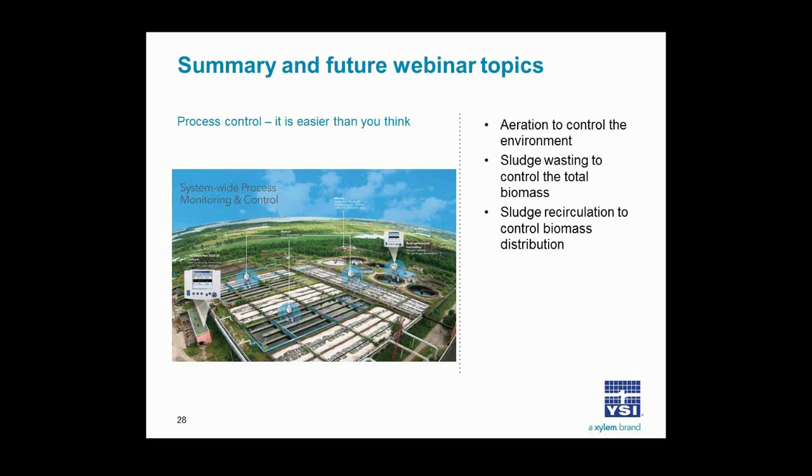Yeah, thanks for the question. Well, it's going to depend on what you have to do. If you have to do nitrification, for example, going back to the chart we showed earlier, the target SRT would be more than 12 days, and I think that's pretty much in line with a lot of utilities. If you do not have to do nitrification, though, a much lower SRT could help you to achieve your goals and reduce your energy consumption and maybe even the number of reactors you have online. Good question. Thank you.